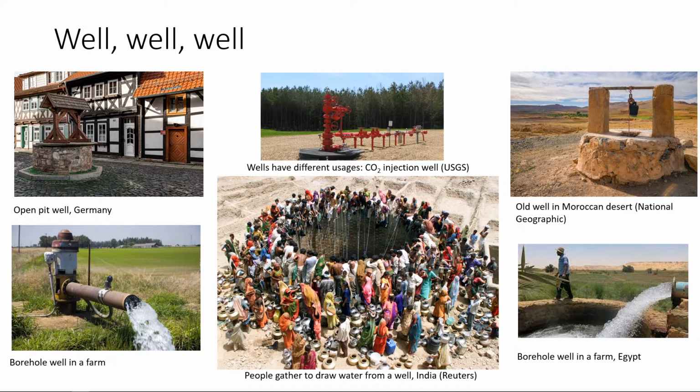What other things for a geotechnical and structural engineer? Why do they use wells? Well, they use wells to lower the water table in a construction project. So if you are a structural or geotechnical construction engineer at a construction project, and you want to lower your water table to put down your foundation or to do basement construction, you just put some pumping wells around your construction site to pump the water out.